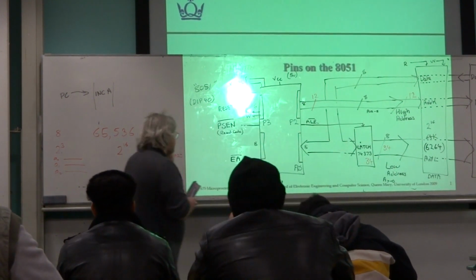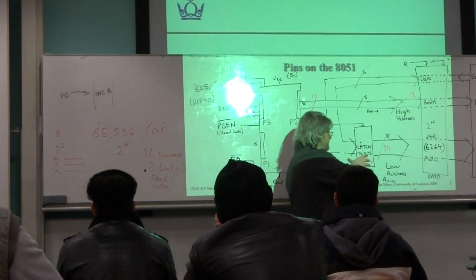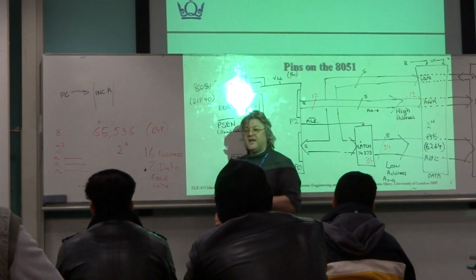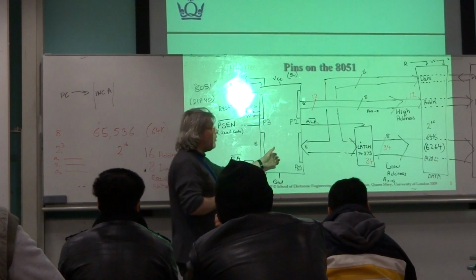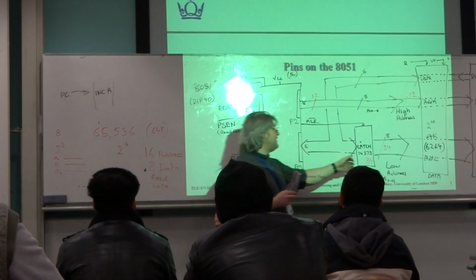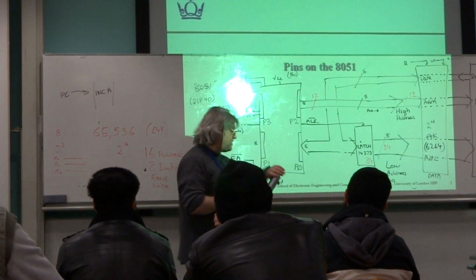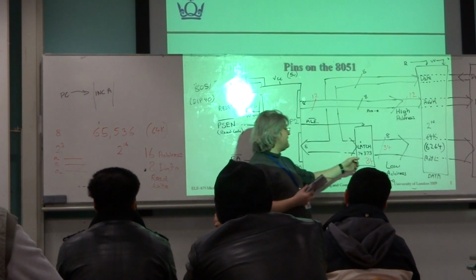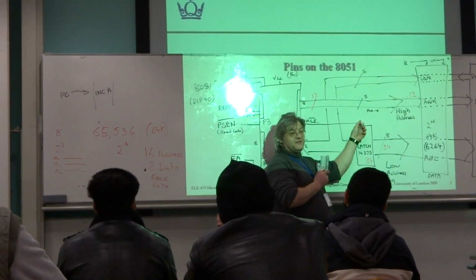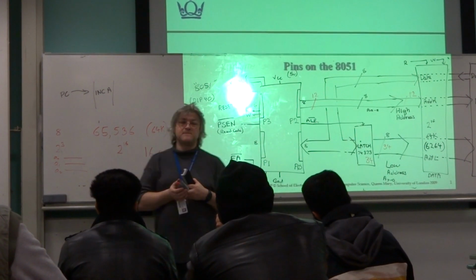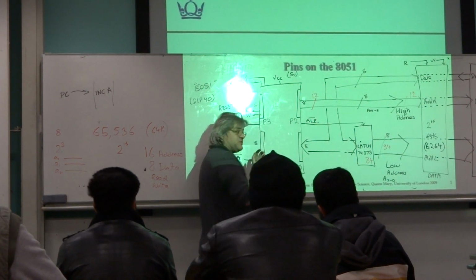Okay, let's recap where we are then. The whole purpose of this very strange thing that I've been talking about is Intel's attempt to not use up all the pins on the 8051 for connecting to external data and external code memory. And Intel achieved this by basically introducing a relatively simple 8-bit latch together with a control signal for that latch, provided you've wired things up this way.